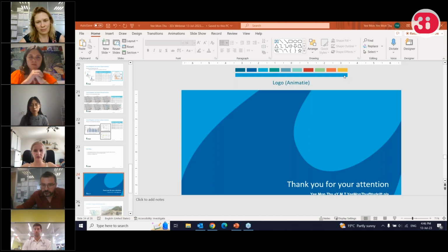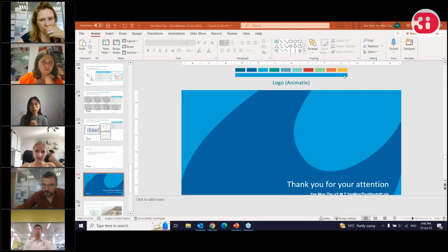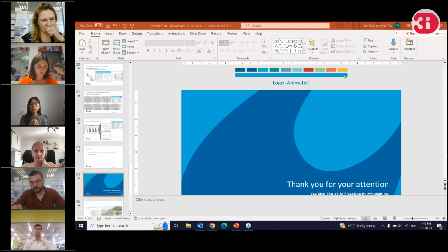My current model is more like a citywide model, a bigger area. So instead of providing data resolution for the whole city, I would like to work on the simulation ability of the 3Di to work with the data resolution. For example, working with the infiltration capacity and playing with the elevation layer to have a retention lake, and also the storage capacity in the swale. But finally, I will try to come up with the potential location with the potential possible data resolution.